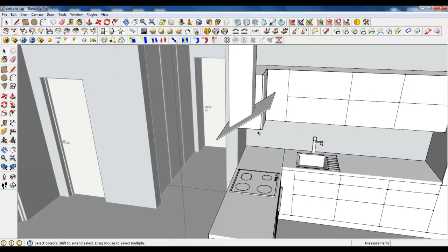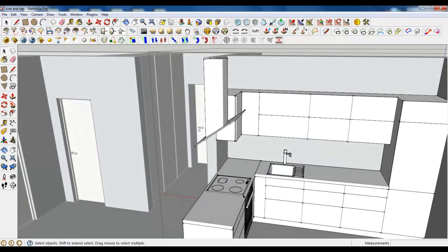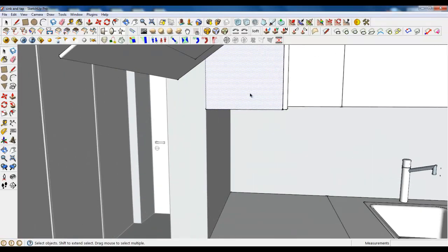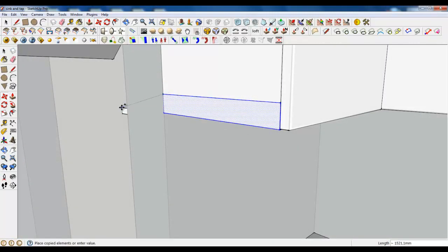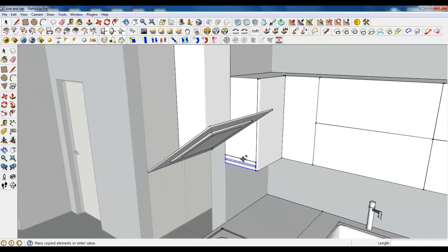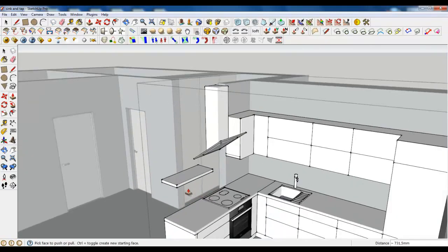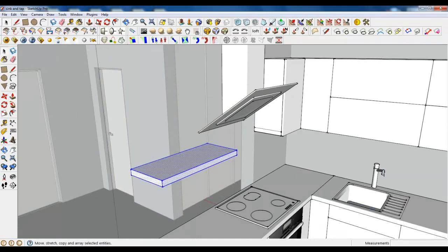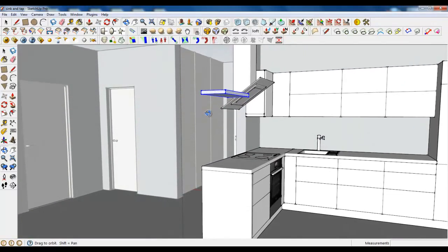Now let's create a shelf. And a shelf is a simple rectangle with 2 cylinders. So let's create it. It's very simple. Type in 40 and copy this plane, not a group, down there. Now extrude by pushing Ctrl and lift it up, for example in this place.